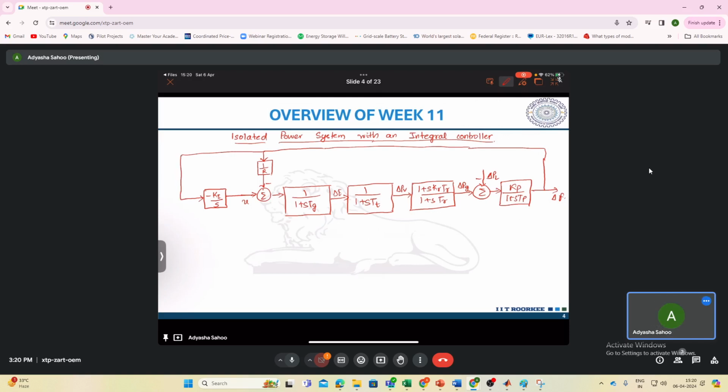So here also we are adding that negative integral control box. That means Ki is greater than 0, so that this whole is negative. Then only the system will be stable. If you give positive feedback, as you know, the system will drive to an unstable condition. So that is the rule here.